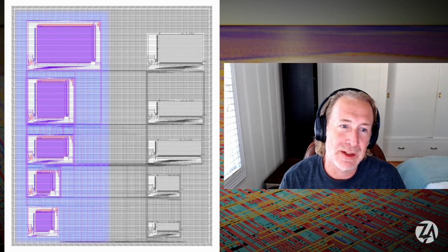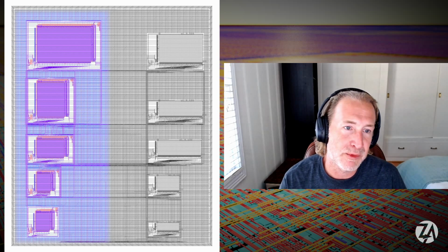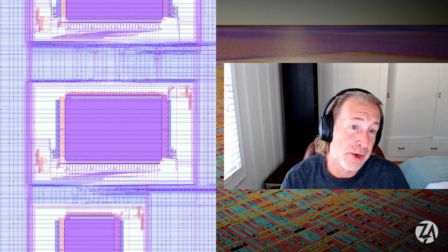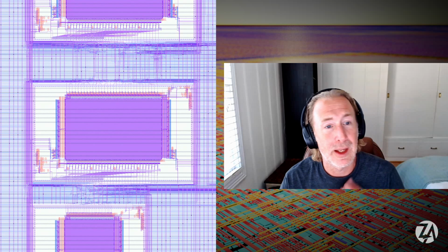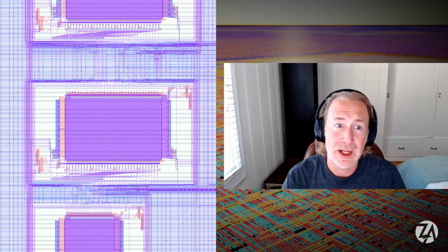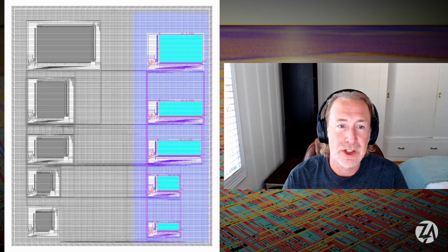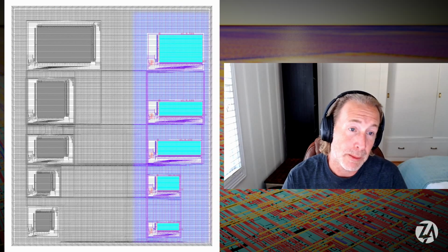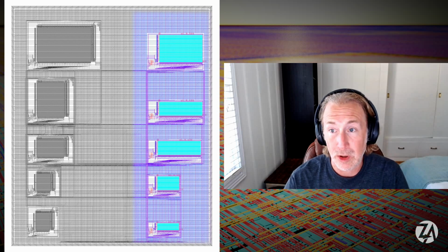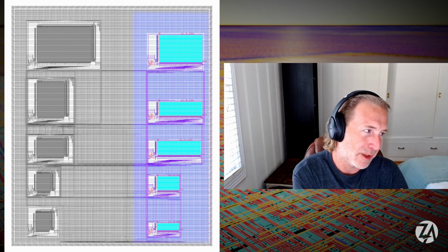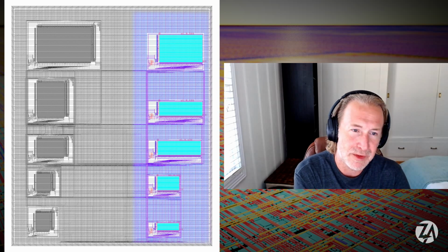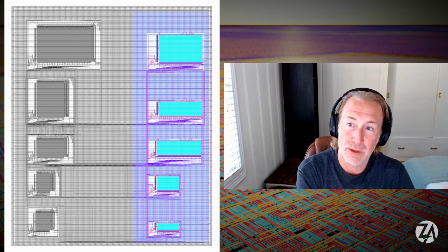But instead of just having the 1 kilobyte size that we taped out before, we basically have four other variants. One is a 1 kilobyte with an 8-bit data word, and then a 2 kilobyte, 4 kilobyte, 8 kilobyte, so kind of increasing size. And then the other addition on this one was the single port memories, which we had not taped out before. The dual port memories basically add two extra transistors to the bit cell, and so it increases the area by probably, I'm ballparking, 10-15%. And so having a single port can be smaller.